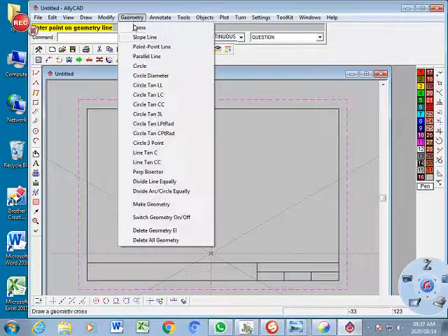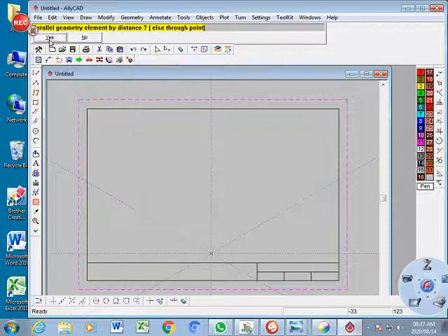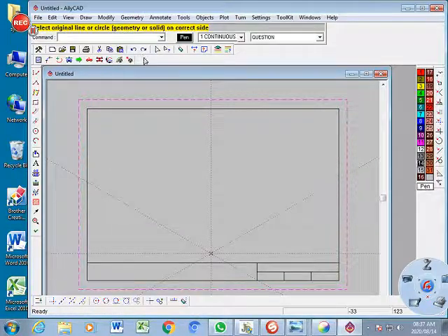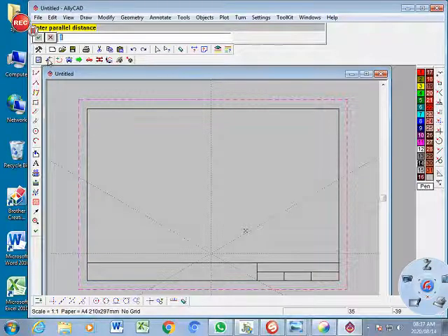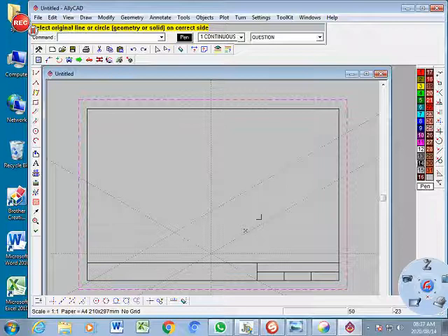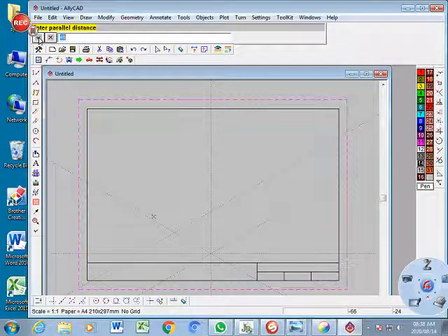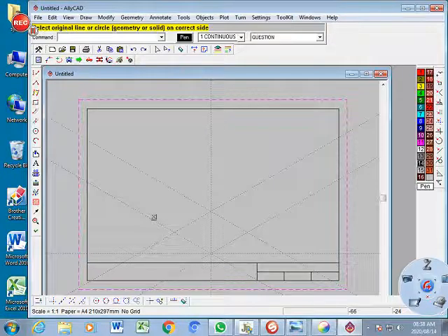So I'm going to go there, parallel, say yes, because it's going to ask me, and then you click next to this line there and it's going to ask you for a total and you're going to say it is 40, the height. You click yes on 40 and it gives you that height of 40, and then you go to this side here, you click next to the line, the 40 still remains, you click yes, and then you have your 40 that side.